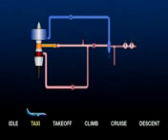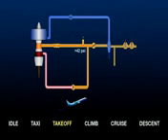At takeoff and climb throttle settings, the engine speed is high. 5th stage pressure will increase above 32 psi so that 5th stage air flows through the check valve. The increased pressure will cause the HSV to close. 5th stage air will be above 42 psi and the PRSOV will modulate to keep the duct pressure at 42 psi. If the temperature is above 390 degrees Fahrenheit, the PCCV will open to allow cooling air to the pre-cooler.